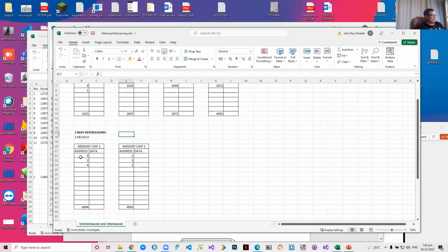Do you follow? The advantage with this is during the instruction cycle, during the fetch of the first memory address, the second memory bank will wait. But during the execution of this, memory chip 2 will load memory address 1, which is actually sequentially the next, into the processor's pipeline. So each memory chip has a pipeline, which means this belongs to pipeline 0, this belongs to pipeline 1.